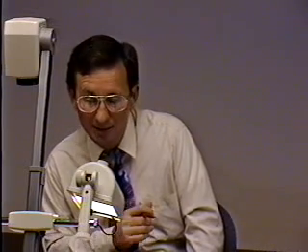And so having done that, what you've just done is set the location of every cross-section. And you have to do that because the stream varies. You need cross-sectional information, elevation versus horizontal distance data, to characterize the cross-sectional geometry of the stream at different locations. But you've set the basic locations of the cross-sections at the very beginning to get the basic data. So there's no way you can solve for delta x's. The delta x's you've set at the beginning. And so what you've got to solve for is the depths.